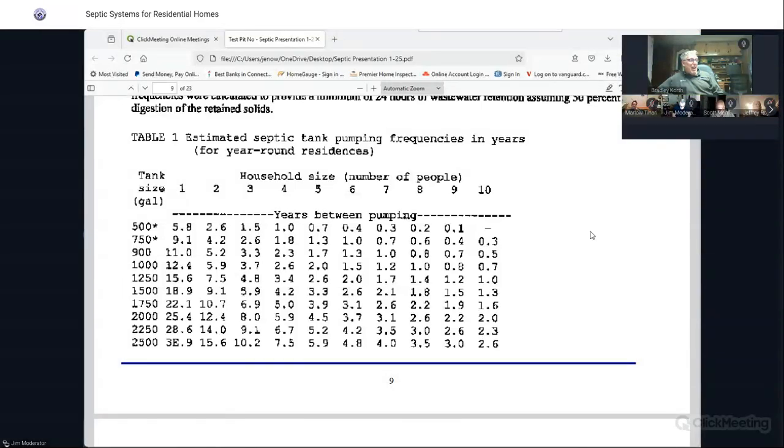Now, probably the saving factor is that, again, I talked about how you use that 150 gallons a day, which has a 50% safety factor. And that 50% safety factor is really for 2 reasons. Actually, the primary reason isn't if people use more water, that's the secondary reason. The main one is, let's say you have a lot of people over at one time, a big party or a big family event, where for a day or a few days you may generate a lot more wastewater than normal. Maybe you typically generate 100 gallons a day, and all of a sudden you go up to 300 gallons a day because you have a bunch of people there.